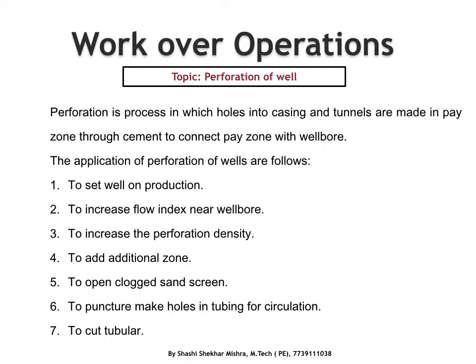First is to put the well on production. It can be achieved in two ways. First, by running the completion with the completion jewelry, and then later perforate the well, which can be done through tubing, or if the completion is run on the TCP with shoot and drop, then later also the well can be perforated with the shoot and drop TCP system.